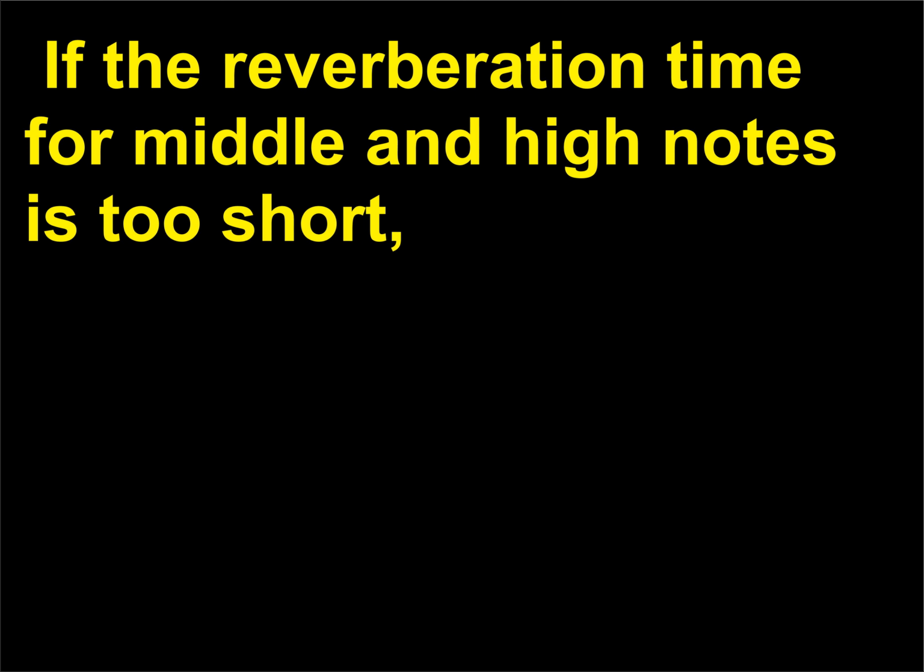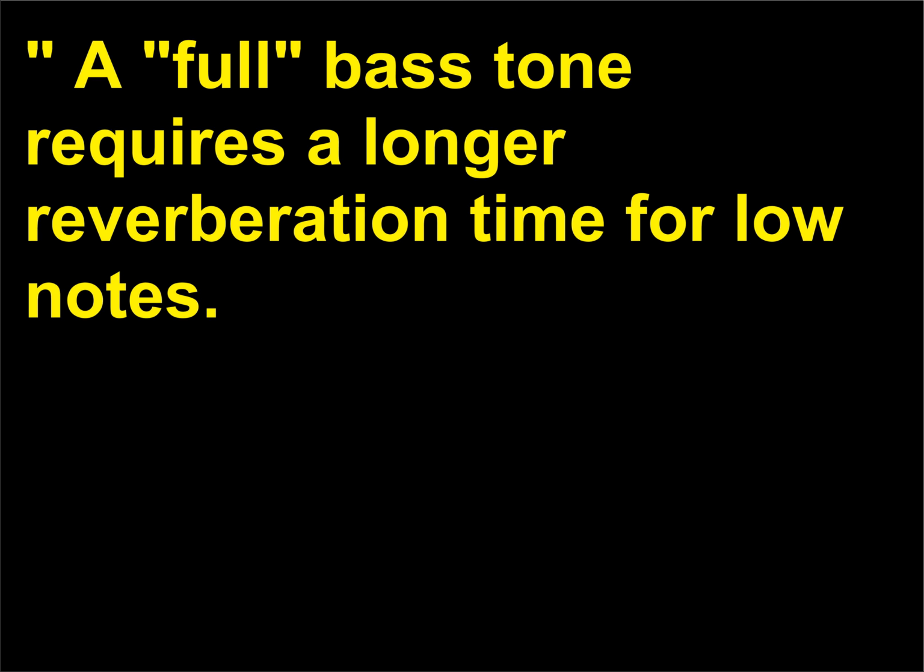If the reverberation time for middle and high notes is too short, the sound will diminish almost instantaneously and the room will sound dry. A full bass tone requires a longer reverberation time for low notes.